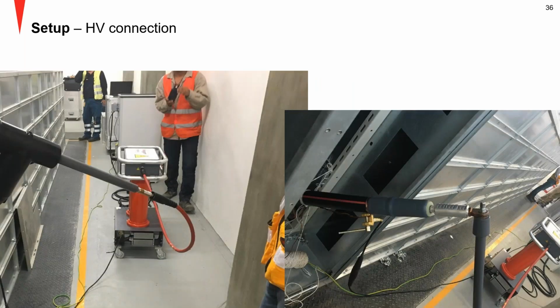So now in terms of setup, a few pictures, field experiences. This, for instance, is a proper setup. You see the PD coupler, you see the source behind there, that's the gray box, a damped AC test set. The high voltage cable, a shielded cable, goes into the coupler on the other side, and an unshielded high voltage cable comes out of the coupler, and you connect it with a proper connector, in this case for this type of switchgear, to the cable. You run the ground to the local station point as you see it there, and this is a proper setup.